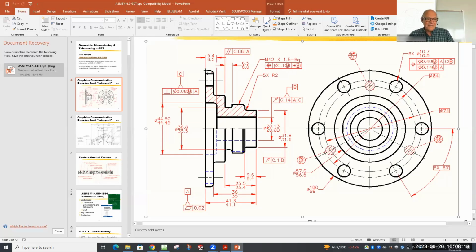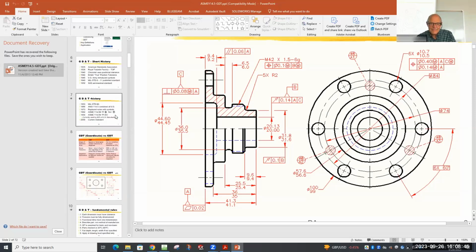One of the most common errors that I have in my mechanical design class is people will put a perpendicularity tolerance on a surface that is actually parallel to the surface they're calling out. And what that tells me is they didn't understand what I said in class. If that's going to be parallel, again, it's going to be parallel to within 0.06. In this case, it's like that left pin example where there's no diameter symbol. So this is also a sandwich. So now let's take a look at what the zones look like.